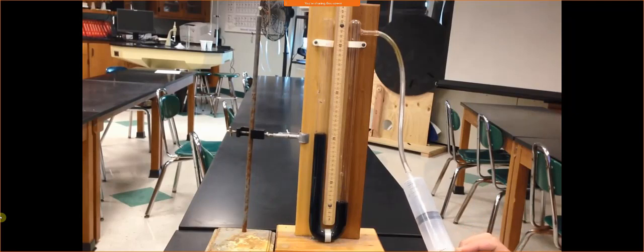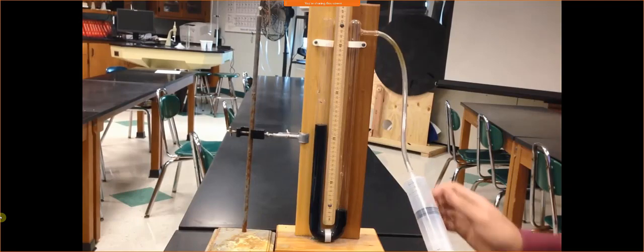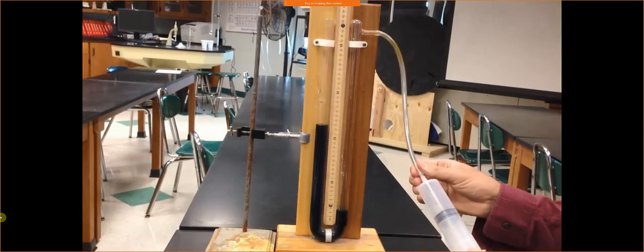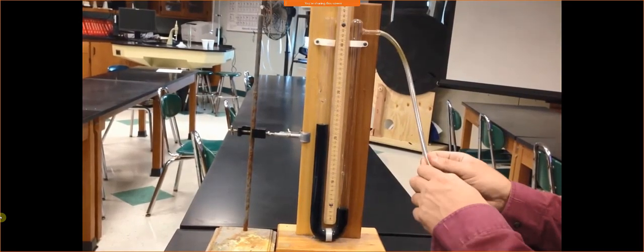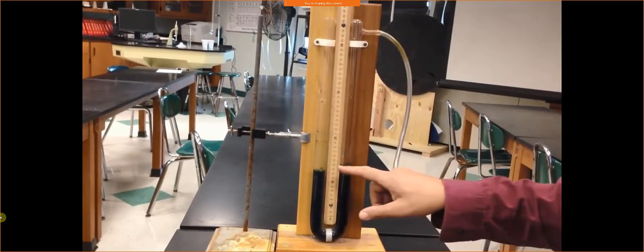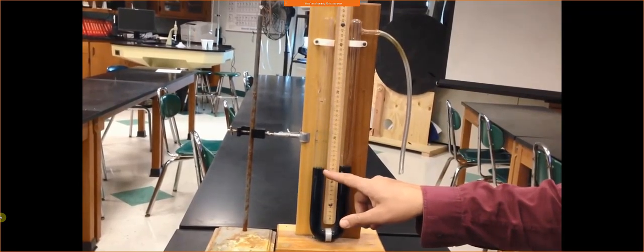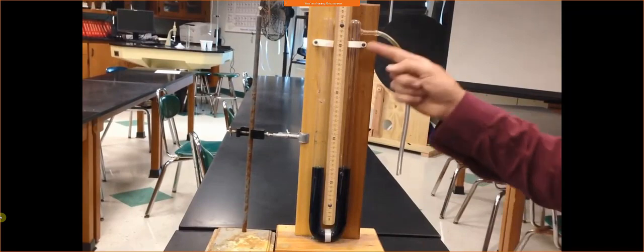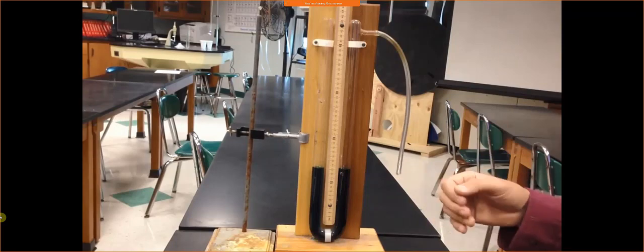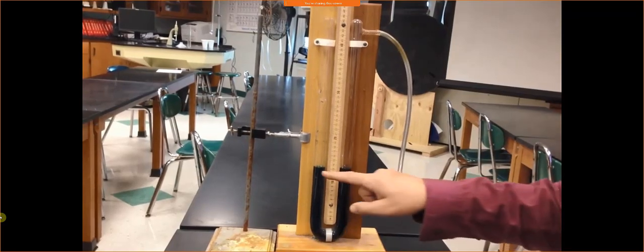The manometer is going to measure that increase in pressure. When the pressure was equal, these levels were equal because the pressure inside this tube is equal to the pressure pushing down in this open container. So the force on this liquid level is the same as the force on this liquid's level, and thus you have equal pressure.